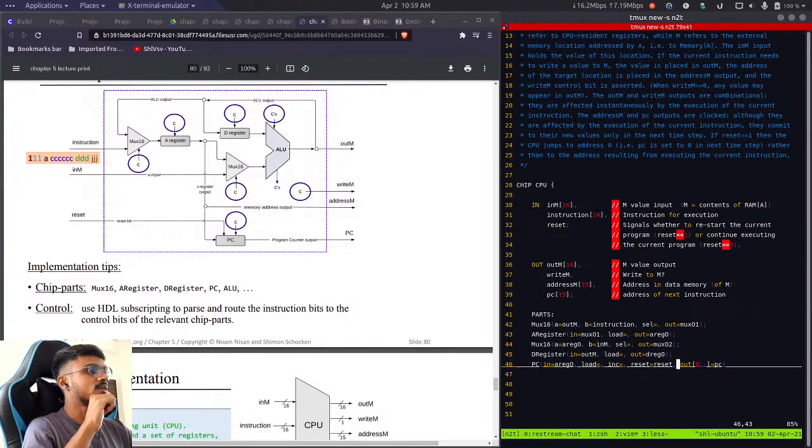As this output is of 15 bits, the last index will be 14th, and we will need to get rid of it. We forgot to write 13 over here. We are only going to select 0 to 13 bits, and we are going to get rid of the 14th bit, and we will pass it to this program counter. All right, we have this thing now.